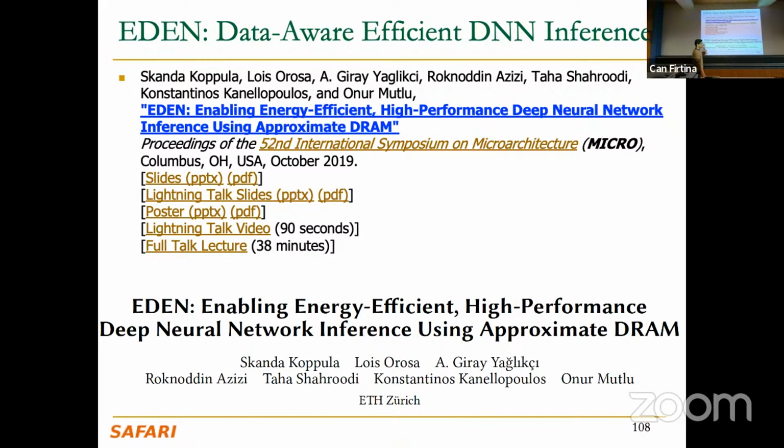The idea is to use what this paper calls approximate DRAM, which is a way of operating DRAM that produces some errors, but at the same time allows you to save a lot of execution cycles and save energy. Even if your DRAM is not so reliable, and sometimes the bits flip, and where you had 1, then you suddenly have 0, that in reality is an error, but in many cases it is probably not harmful enough to make your system not work, right?